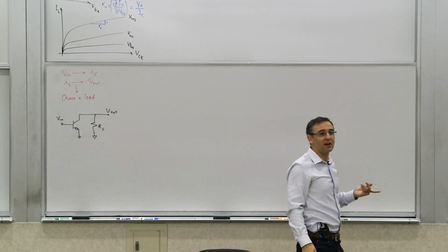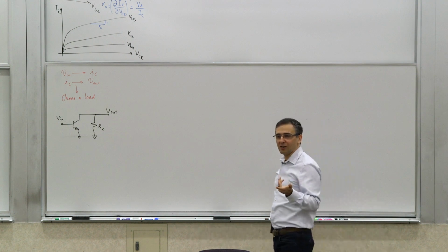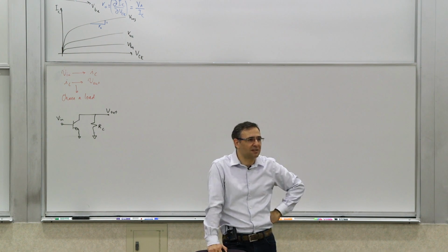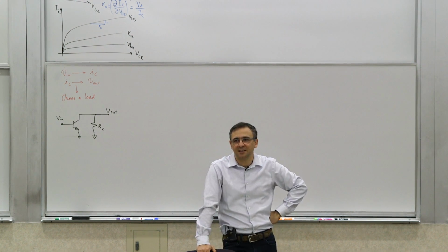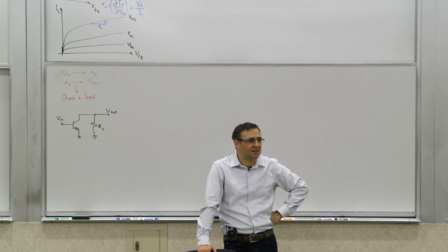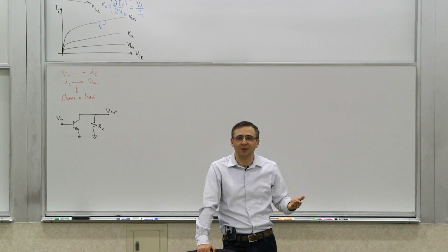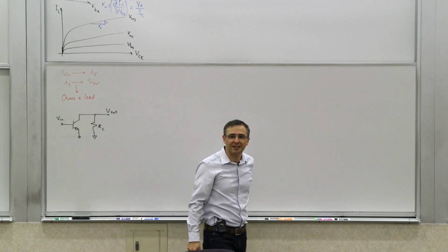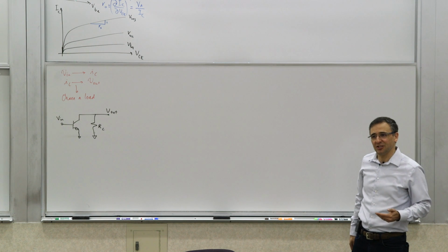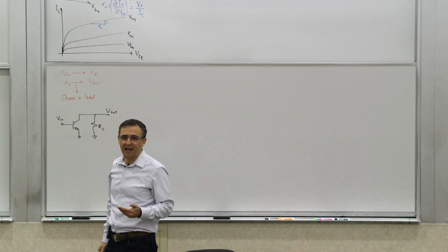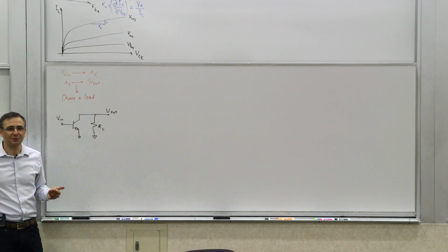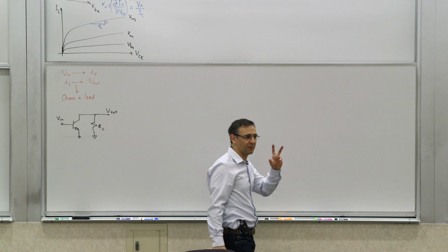And there was another argument that you could have given me, an even simpler, more physical argument. That was a good argument, by the way, don't take me wrong. Why would this not be an amplifier? The way I've drawn it, where's the power coming from? There's no source of power, unless there's some magic source of energy inside this thing that you can tap into. There is a source of energy in there, which is the thermal energy, but thermodynamically it is the highest entropy source, so it's not possible to extract a lot of useful work out of it.